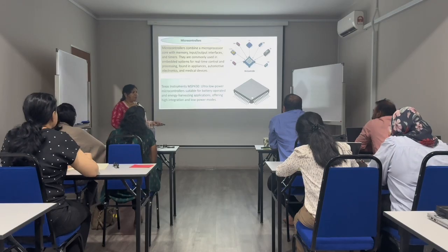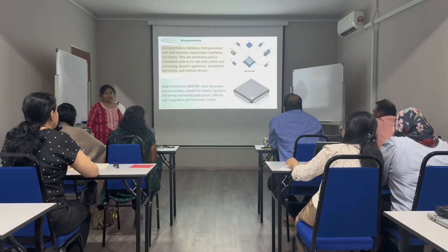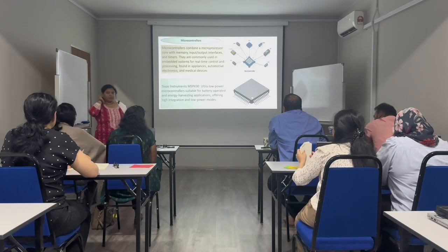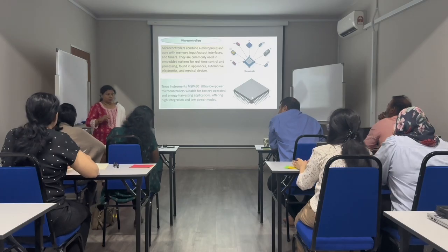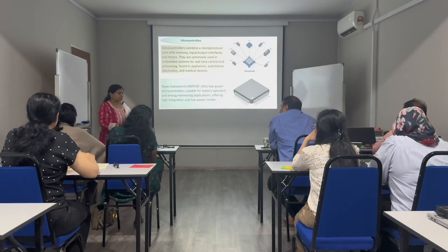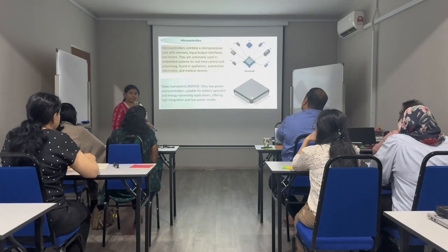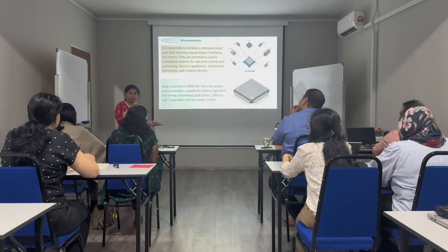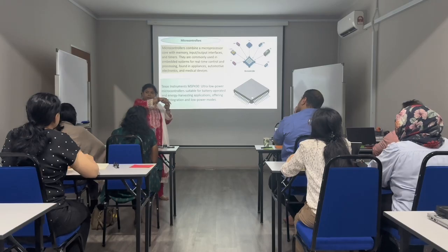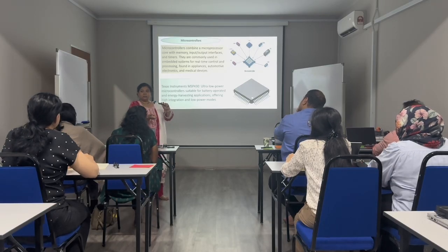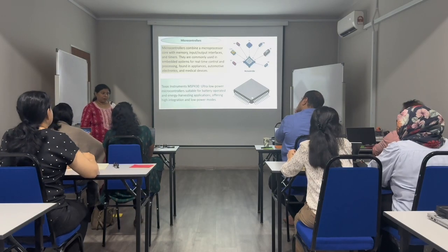If you are going to perform multitasking or multiple applications, then we will have a microprocessor. When you have embedded applications, to do some specific task, for example a washing machine, the IC there is not a processor, it is a microcontroller, because it has to process all the data, digital and analog, everything clubbed inside it, and it has only a few applications. It can wash, it can spin, and it can rinse. Those few applications can be carried over to microcontrollers.